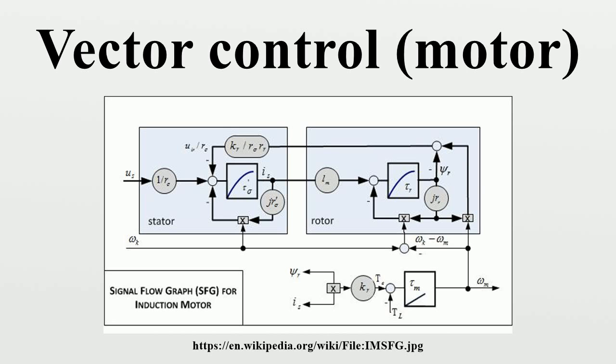Sensorless control of AC drives is attractive for cost and reliability considerations. Sensorless control requires derivation of rotor speed information from measured stator voltage and currents in combination with open-loop estimators or closed-loop observers.